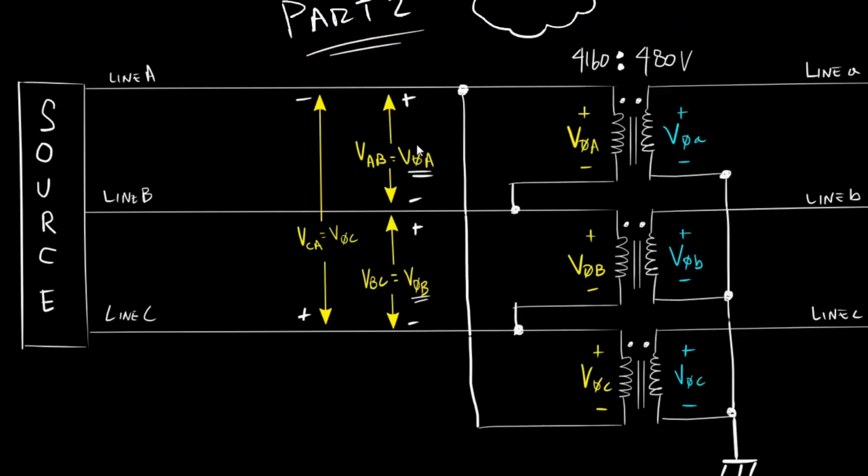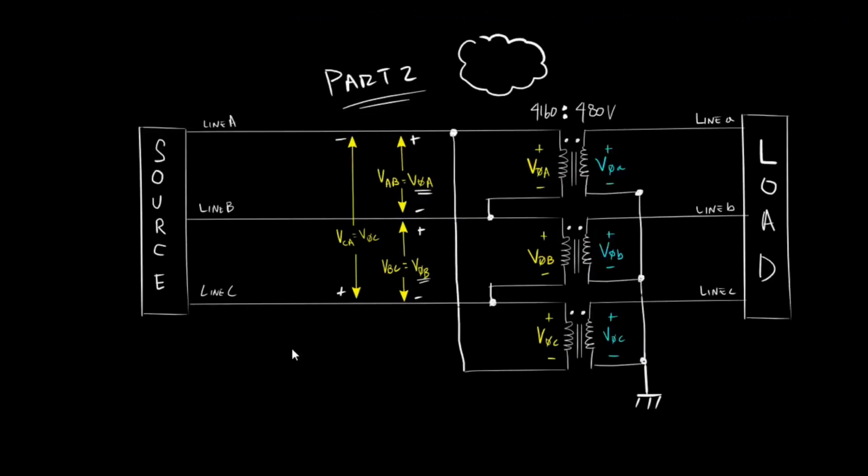So in this video, we're going to further talk about these voltage quantities on the delta side. Now to begin, let's clarify something. The delta has no ground, right? But there is a ground somewhere in our source. Some generator in this source is tied to the ground, and that ground is the reference for this transformer. So we're going to assume that it's this particular connection, so we know what the ground is.